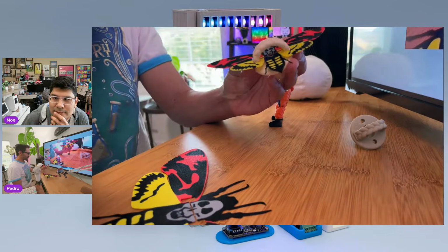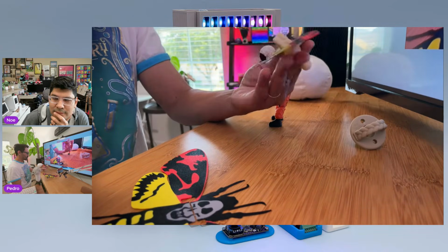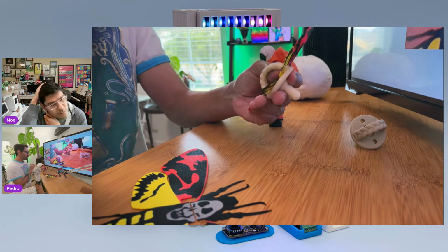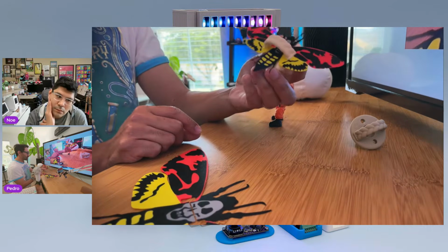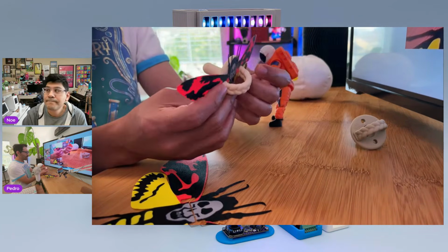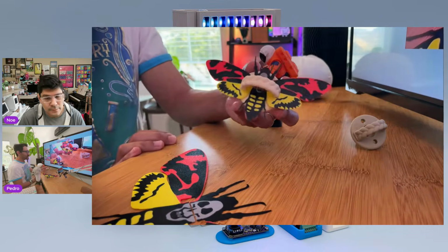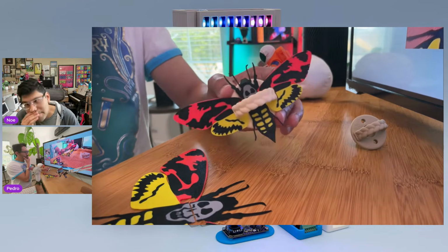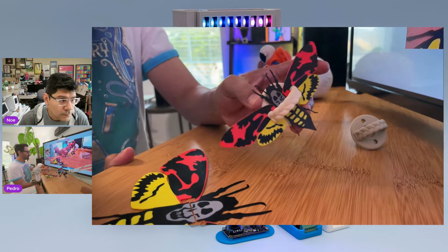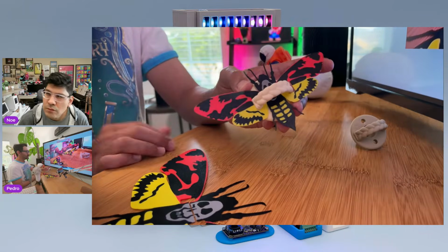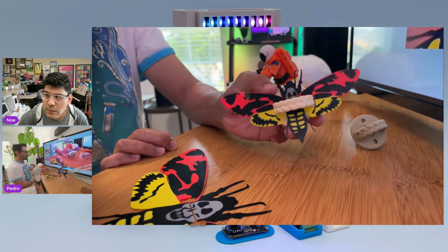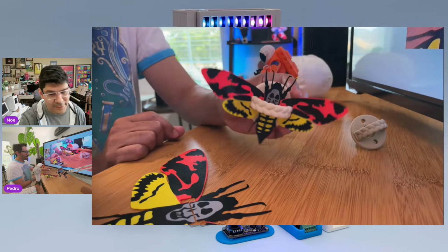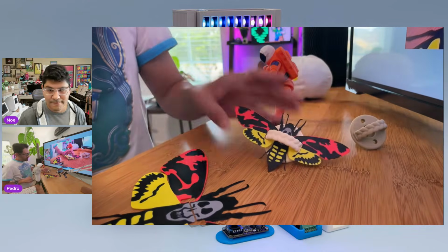What else in terms of settings? That's all I learned. Yeah, just your standard TPU default settings. Yeah, standard TPU. I'm using the high speed TPU from Overture. Oh, Overture. Okay. And for Bambu Studio, they have an AMS specific flexible profile. That's right. Yeah, when I was doing the profile setup, it would not let me do it if it was not the AMS specific TPU. Yeah, you can get some real nasty buckling, I guess, if it wasn't the right material. Exactly, yeah. Okay. So it's pretty cool.